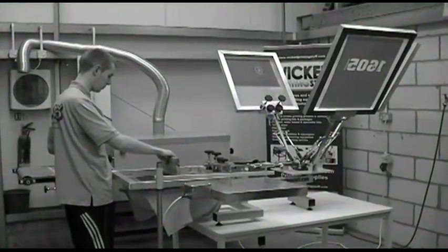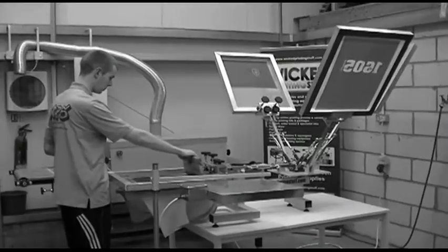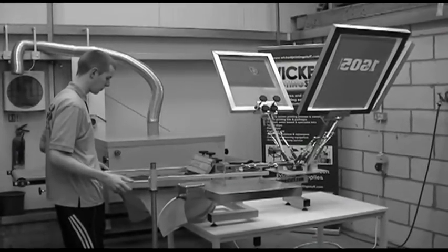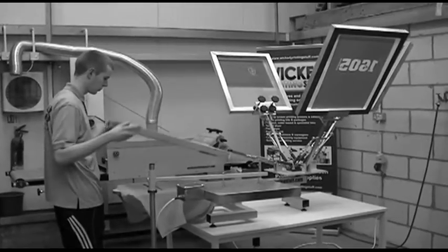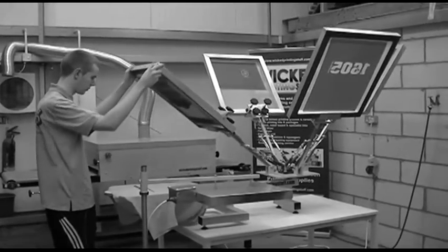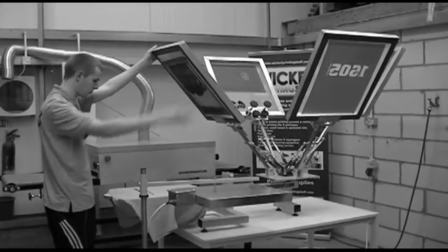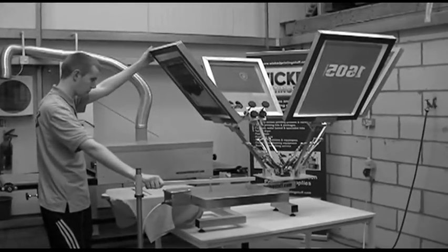It is now time to dry and cure your print. If you are printing more than 1 coat of ink for the same image, or printing a multicolour image, you will need to flash cure your ink by using a flash dryer or heat gun between each print. Once your print is dry to the touch, you can apply your second coat or next colour.